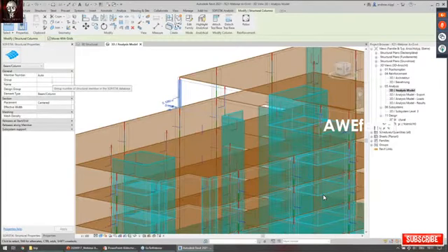So, for example, you can give the element a group number, you can give it a name, or what is new, you can decide whether the element should be calculated as a standard beam element, so a standard beam element with all 6 degrees of freedom being active, or instead analyze it as just a truss element, or you can also analyze it just as a cable element, which can only receive tensioning forces.